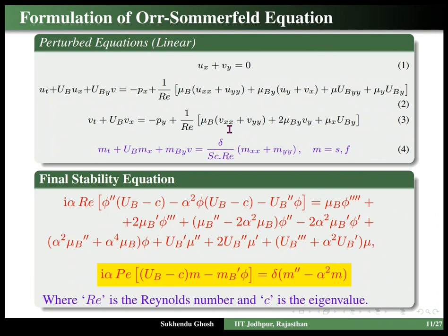In linear stability theory we can take help of Orr-Sommerfeld analysis to capture the instability in a much easier way, and that's why you have to calculate the stability equation, known as the Orr-Sommerfeld equation, after applying the normal modes. These equations are given here. So this is the complicated Orr-Sommerfeld system for stratified flows. Here many terms are there, and that's why it is known as the generalized Orr-Sommerfeld equation. In the basic Orr-Sommerfeld equation there are very few terms, but here, due to the existence of viscosity stratification and viscosity perturbation, many extra terms are there.